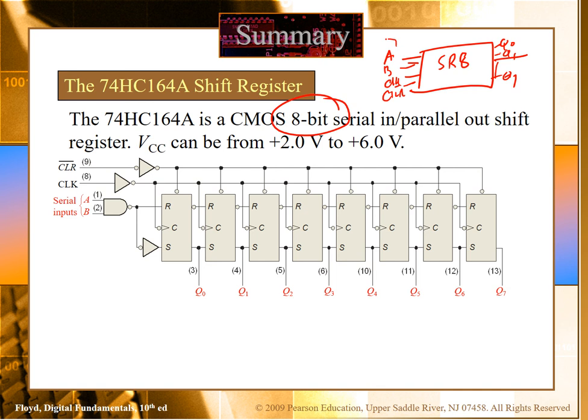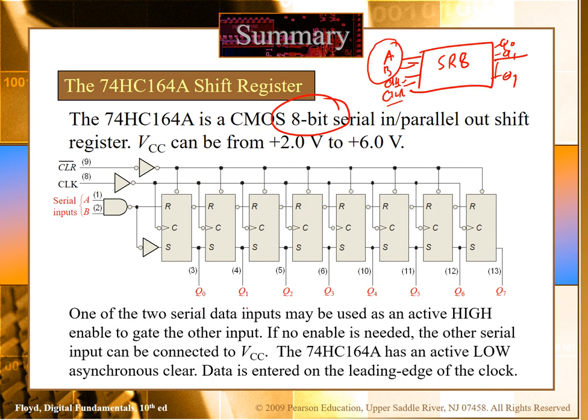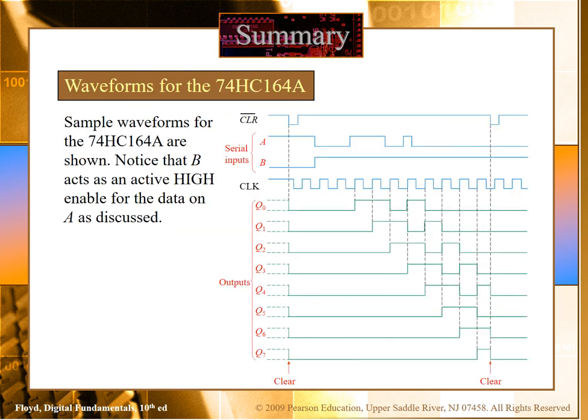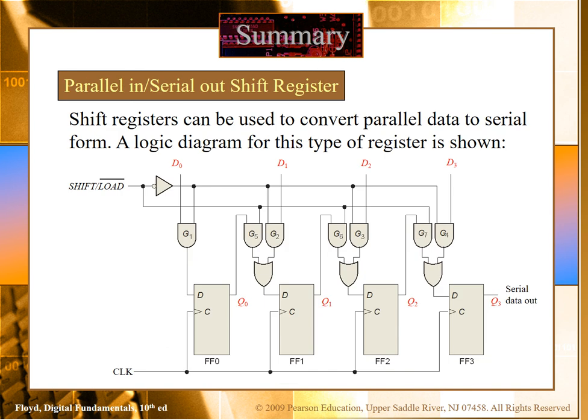You input the serial data here, and at the edges of the clock you will get the output data. This is serial in, parallel out, so you will get the parallel output data here. We will see this waveform example in the live session.